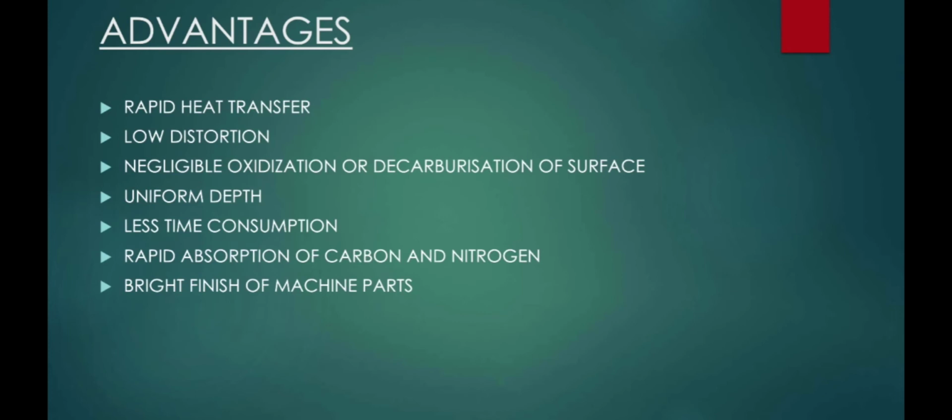It gives rapid heat transfer. It produces only low distortion to the steel, and negligible oxidization or decarburization of the surface. It gives uniform depth. It is less time consuming, with rapid absorption of carbon and nitrogen, and it also provides a bright finish to the machine parts.